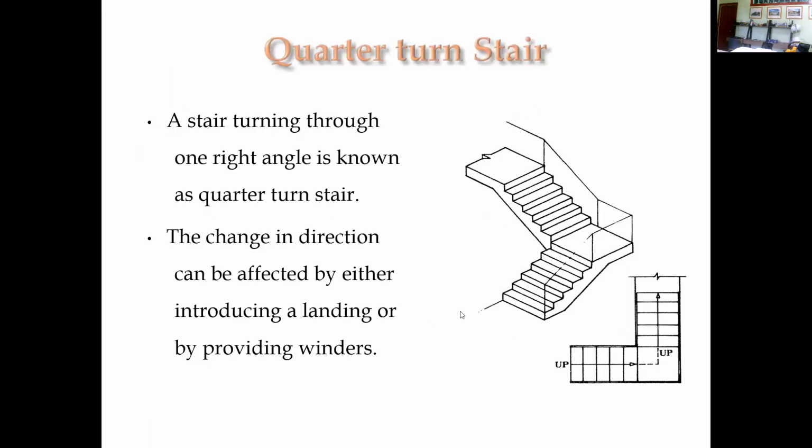So this is another quarter turn stair. There is one right angle, known as the quarter turn stair, and the change of direction can be effected by either introducing a landing or providing winders. Winders are where you cut the landing into several pizza pie shapes.